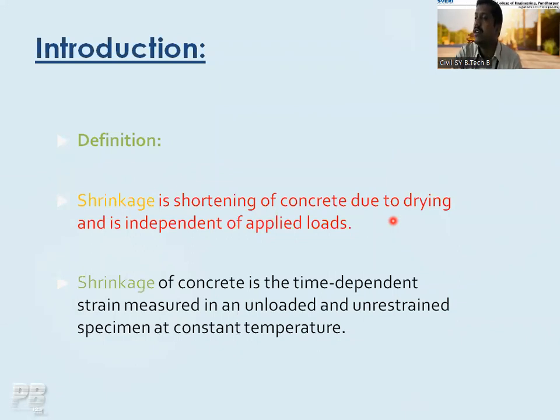Shrinkage of the concrete is the time-dependent strain. What is shrinkage? It is the time-dependent strain measured in an unloaded and unrestrained specimen at a constant temperature. It is very important for us to understand this sentence. That means whether we are applying load on the concrete body or not, it is not the major factor we need to consider. It is independent of the applied loads.